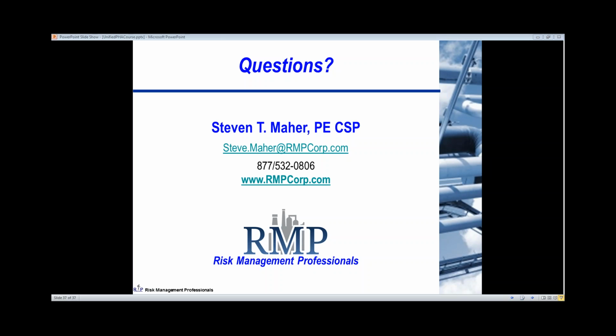And I didn't quite understand the first part of the comment on the near misses. It is a requirement when you're looking at updating a HAZOP study to specifically bring into play incidents that have occurred, and your incident reporting system should be picking up near misses. Now, the reality is there's a lot of challenges in doing that.